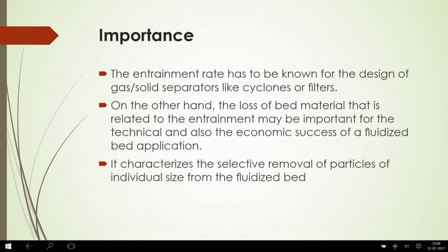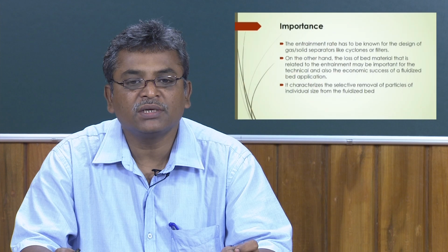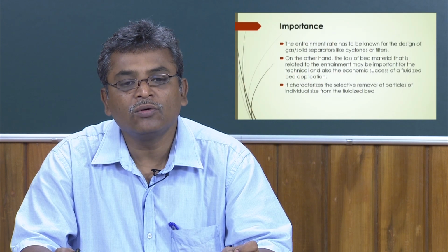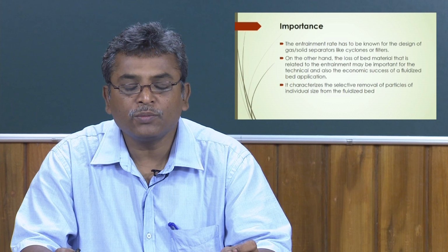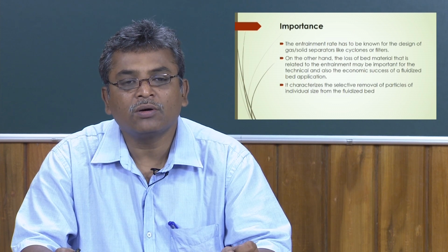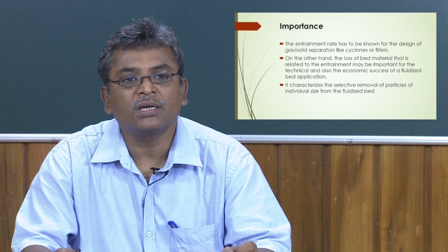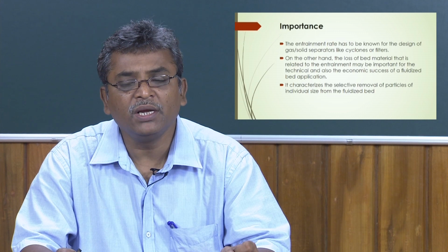Now, why is it important to know the elutriation characteristics in the fluidized bed? The entrainment rate has to be known for the design of gas solid separators like cyclones or filters. In the same way, elutriation is also important because it gives you the classification of the solid particles: which particles will go up, which will go down, what the interaction of the larger or coarser particles with the smaller particles should be, and because of those interactions how the solid particles would be segregating by